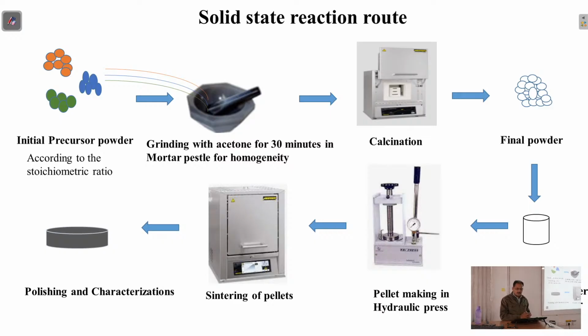To begin with, this is the usual procedure to first of all make a piezoelectric material. What we have generally been using are in pellet form. Depending on which piezoelectric material you want to make, you have to have these precursors. The precursor powders in the stoichiometric ratio you first mix, then you put it for calcination at high temperature, so then the desired material powder will be made.